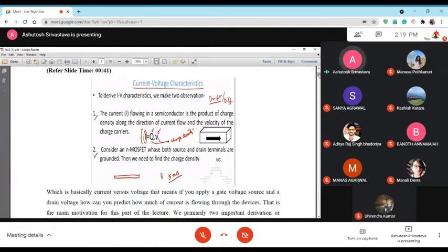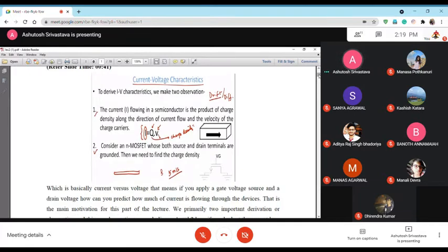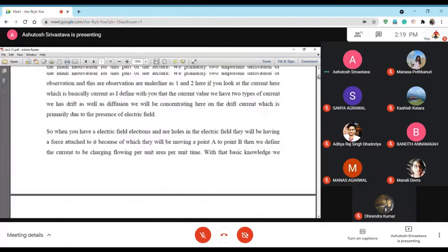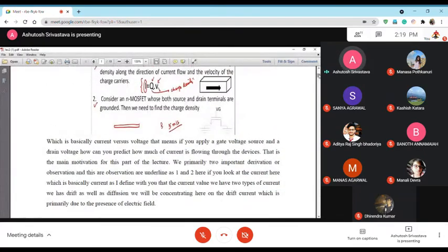There are two major electric fields that we are talking about, which is why it is called field effect transistor. The first one is the vertical and the other one is horizontal. The vertical comes because of the gate voltage, and the horizontal comes because of the inversion layer formation along with the voltage that you give towards the drain side of the MOSFET configuration.